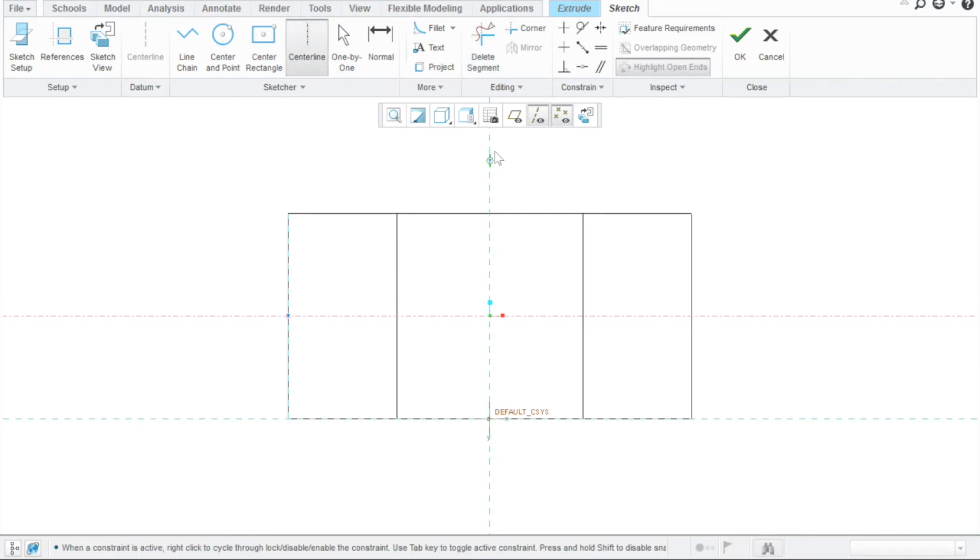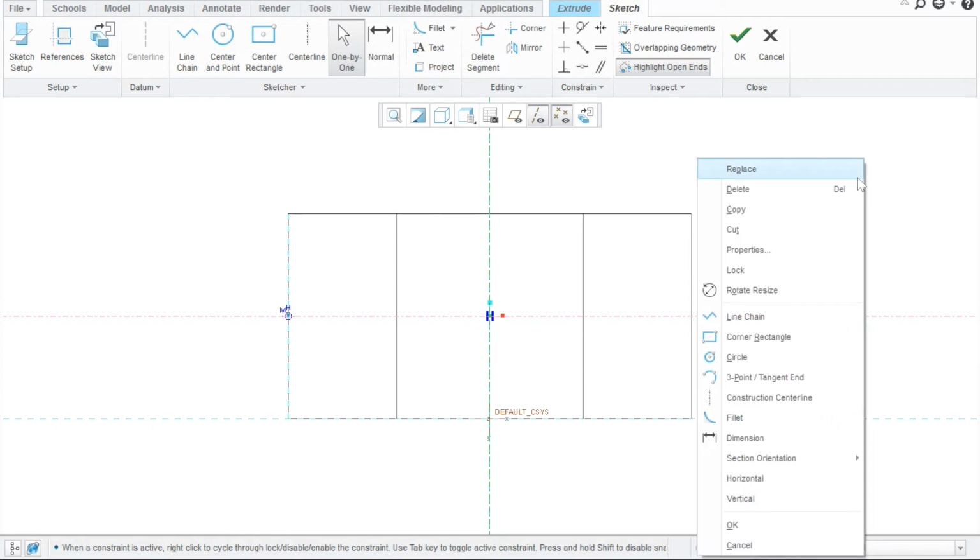Also, we're going to have a center line. We call it a vertical center line. It's good to have those center lines as a reference, so you can use it for symmetrical purposes. So you want to come up with a symmetric. This way, your sketch will be strong or fully defined. In SolidWorks, they say fully defined, but here we say converting the sketch from weak dimension to strong dimension. So okay, next we want, let's just put, by clicking right click.